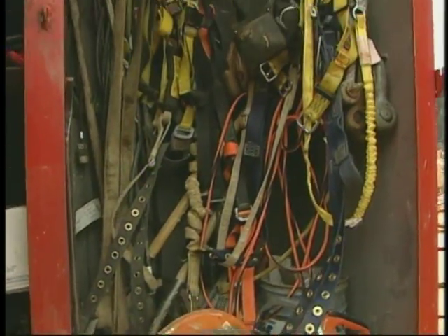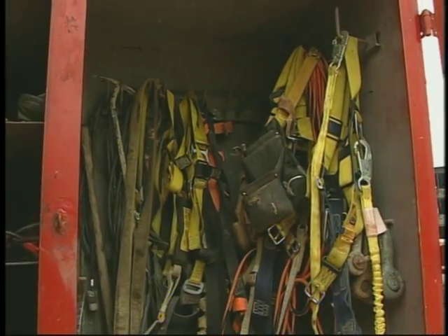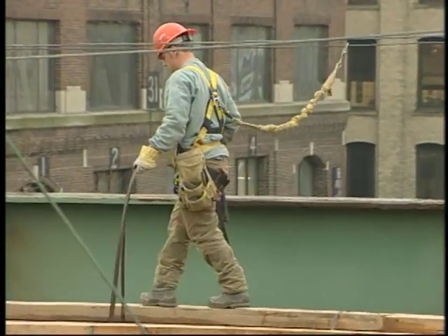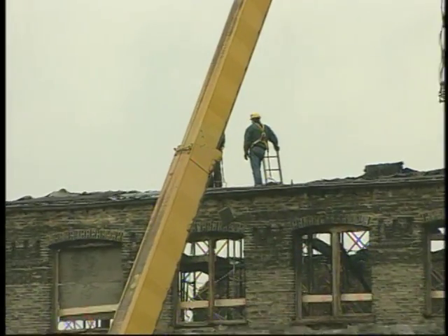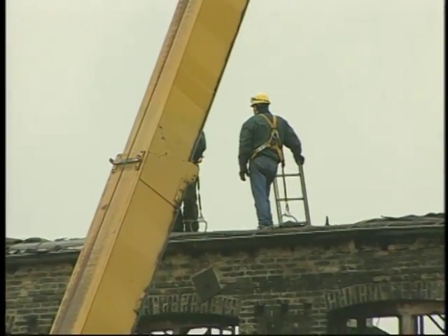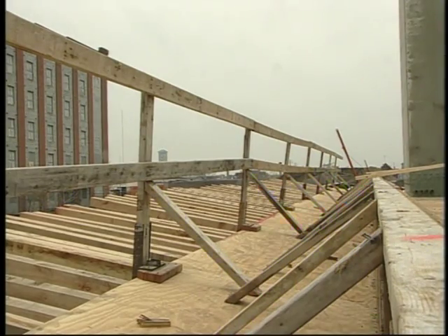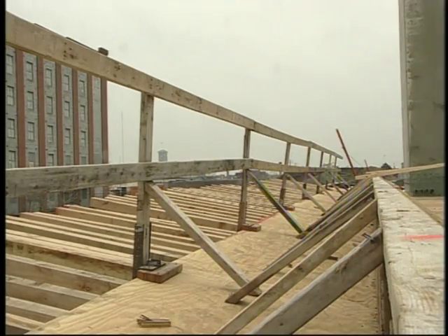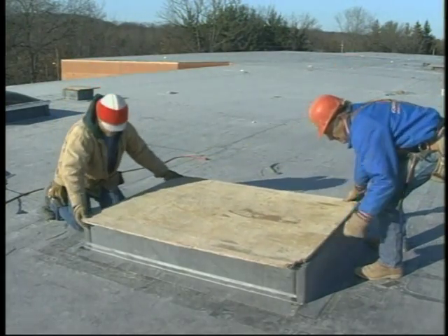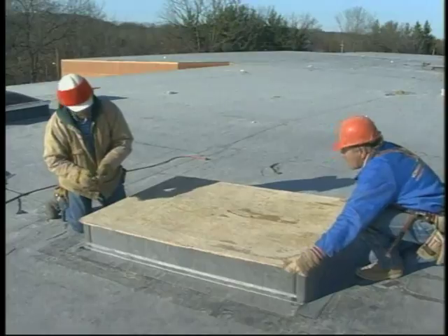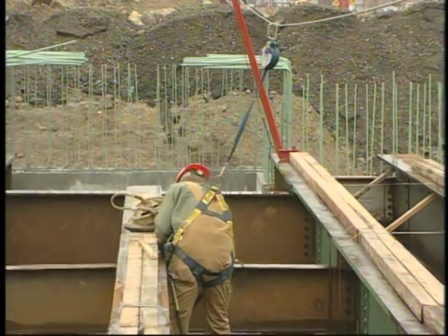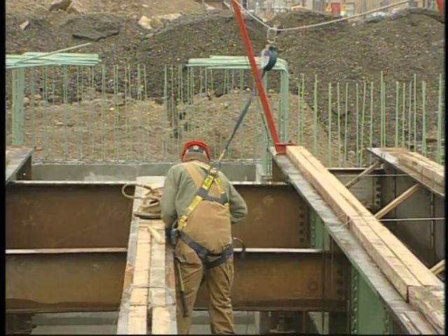Third, take advantage of the safety devices your employer provides. They're there for your safety, so you should use them. Your employer must provide some method of fall protection when you work at heights. Guardrails with toe boards are methods that protect you from falls. They also protect workers below from falling objects. Guardrails are used on scaffolding and around the perimeter of buildings. Covers must be used over floor openings to prevent falls. In certain situations, fall arrest systems must be used.